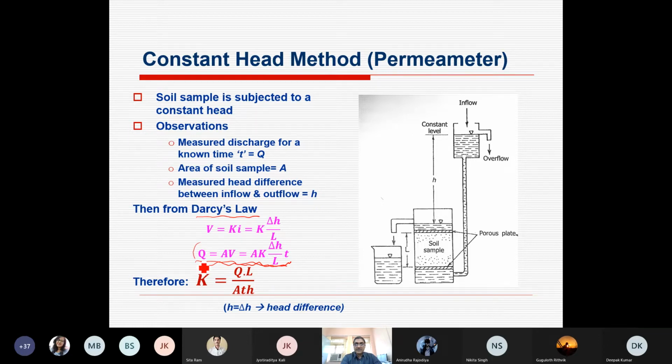In time t, or per unit time, that is flux, which I told you in the class is simply the relationship between hydraulic conductivity and hydraulic gradient, that is delta H by delta L. So v, that is flow velocity, is simply related by Darcy's law to hydraulic conductivity and hydraulic gradient.